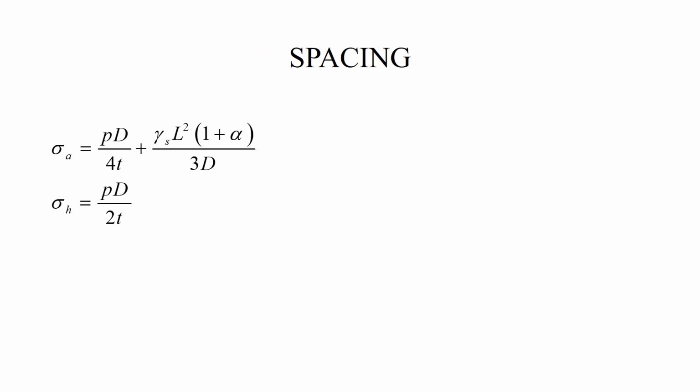So here I have to decide which stress to choose. And in principle, it could be either one. But in all practical situations, in every structural code that involves analysis of pipelines, this is the primary stress of concern, sigma A. That's how typically the numbers end up.